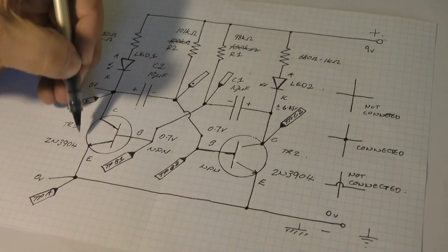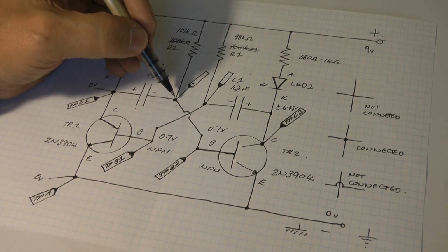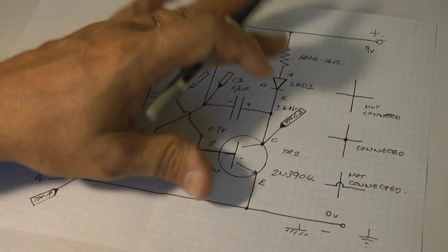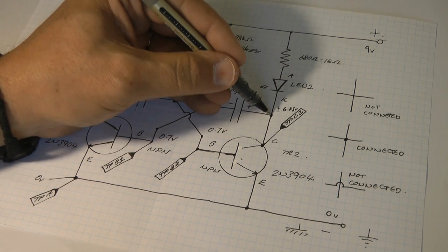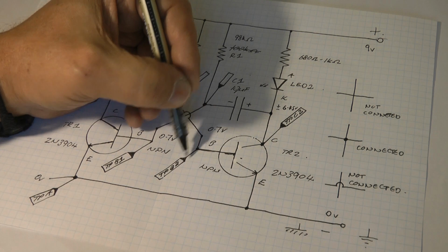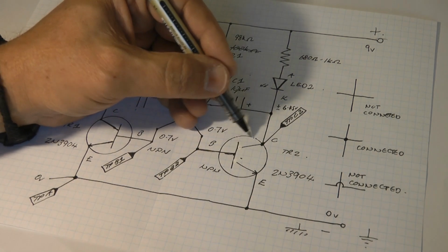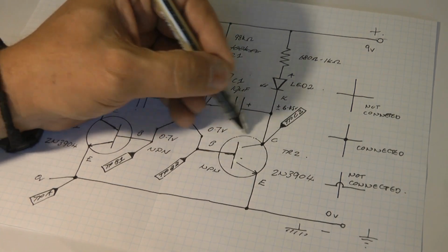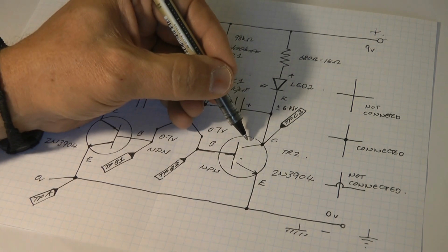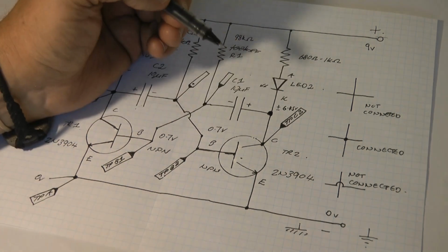Even as this transistor came on and this went to 0 volts, pushing this down to minus 4, 5 or 6 volts, if this transistor had in fact started up when the circuit started up, that would have been at 0 volts. But the moment this transistor on the base was knocked down into minus territory, this would have opened up the transistor in terms of comparing it to a switch. It would have turned it into an open contact type switch, and then this voltage here would have started to climb up to a higher voltage.